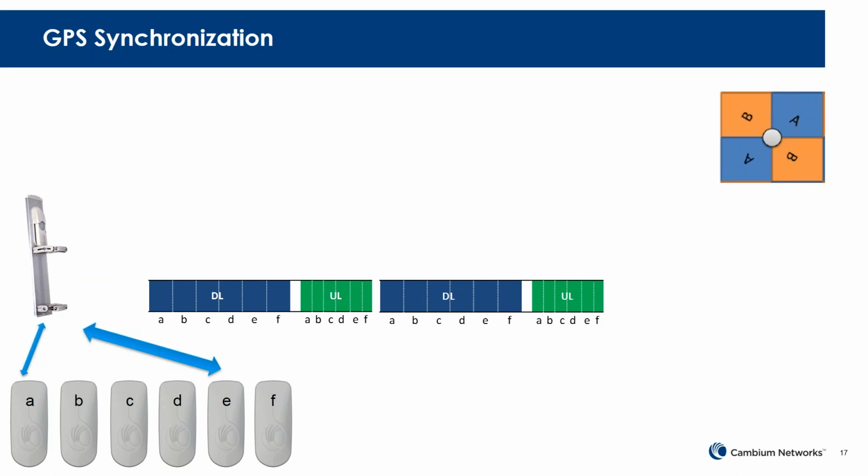Sometimes you deal with competitors' interference, radios that you have no control of. You can't log into them, you can't change the channel on them, you just have to work around them. So GPS synchronization is a great way to eliminate self-interference. Keep that in mind.